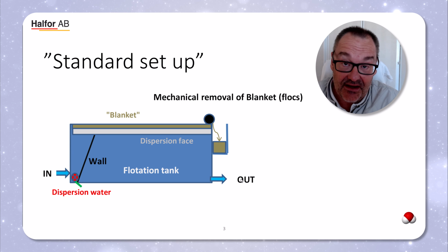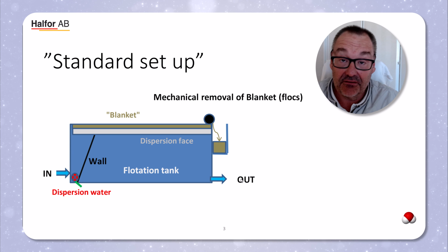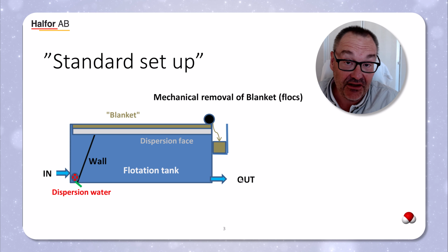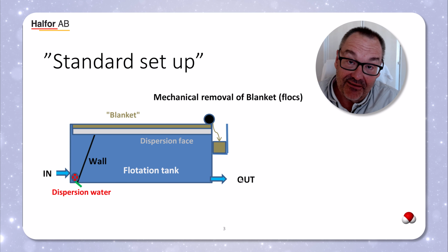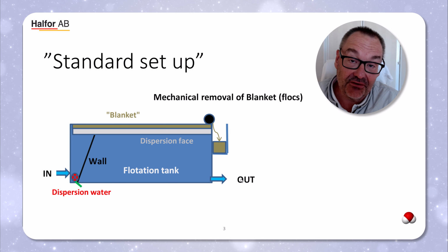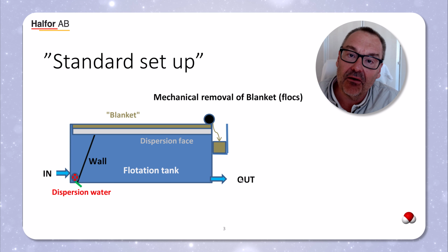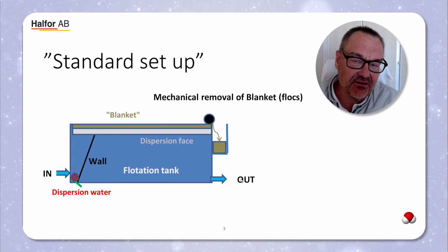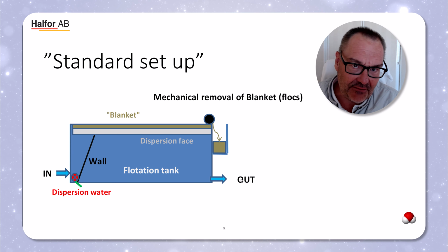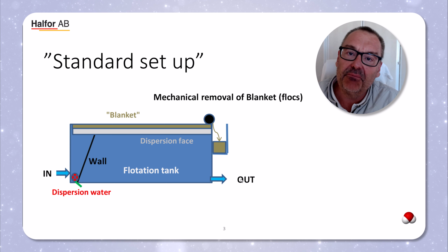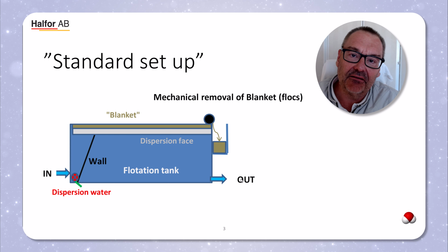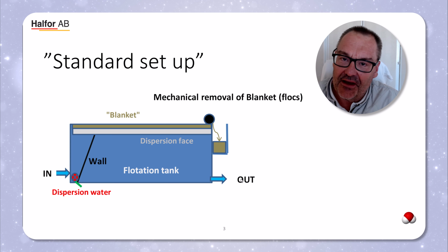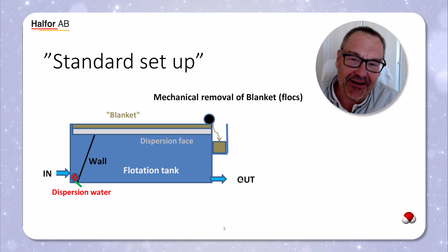Now, this is a standard setup, and there are many good suppliers globally of flotation units and turnkey plants for flotation. But always remember that it's your particular water that in the end will decide how a treatment unit will work. So my suggestion is always to start with a small lab scale or a pilot plant before you decide on investing in a full-scale plant. That is my suggestion based on my experience.